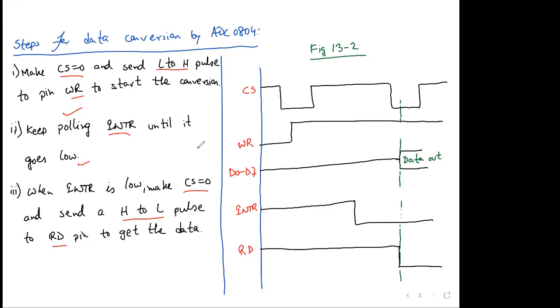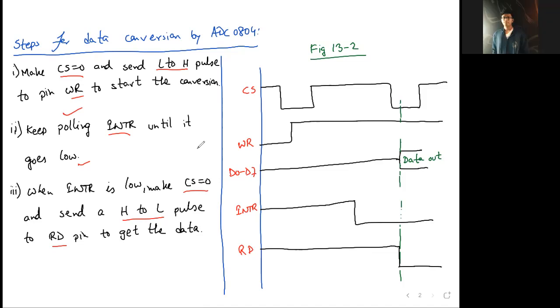Now I get your question. The question is, what if we don't provide the control of the CS pin to the programmer, and rather we make sure that the CS pin is always low, so that the chip is always active? Yes, sir. Okay. Now, we talked about transients. Do you remember voltage transients? We try to avoid those things, but still, whenever we are doing this type of conversion, very often we might face voltage spikes, unexpected voltage spikes.